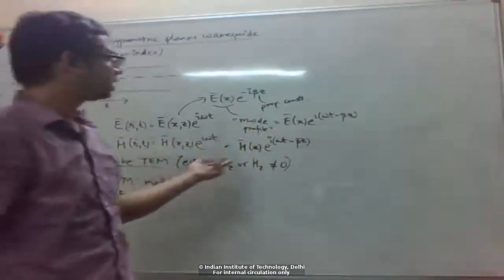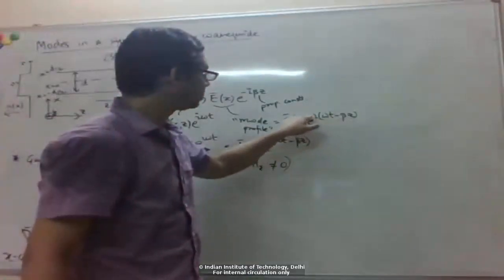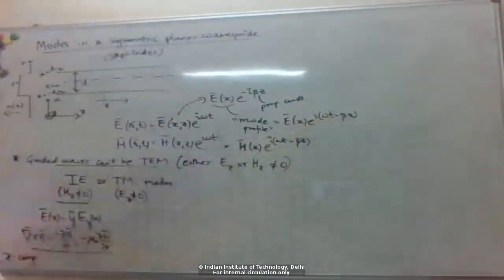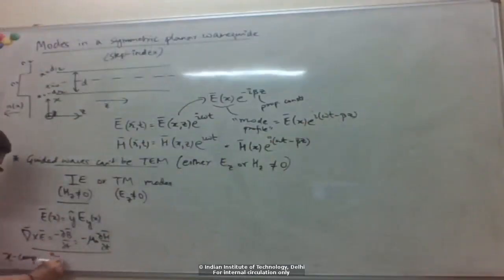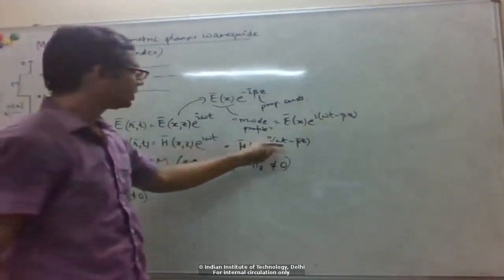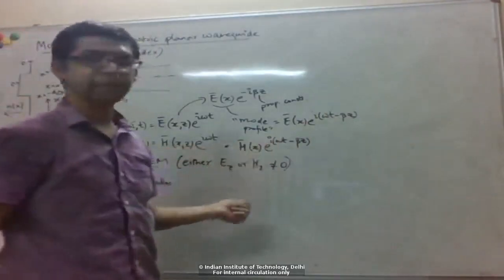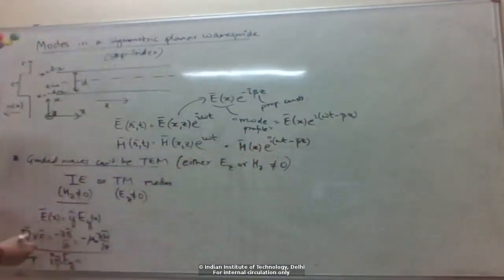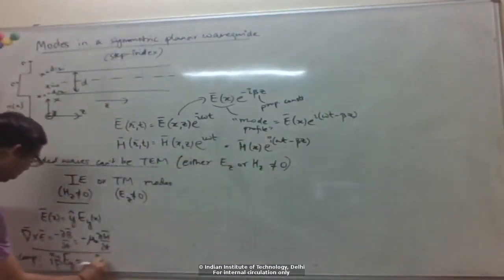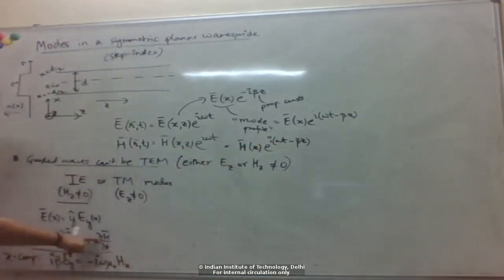So when we take the derivative with respect to z, we get this minus i beta out in front. So basically, with the x component, we get i beta times Ey, and then here we have a time derivative, and we'll just take this i omega out front because that's the only time dependence, and Hx because we're taking the x component.